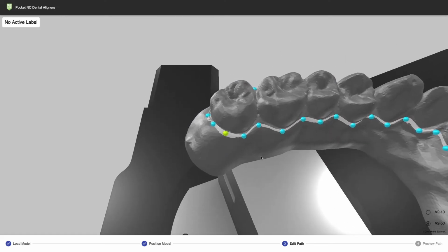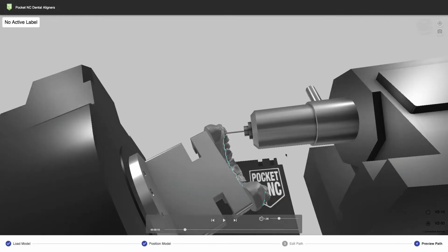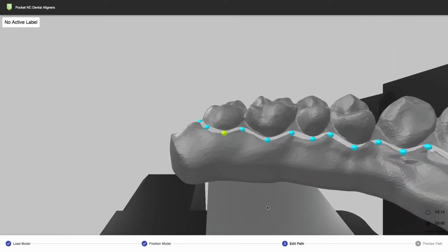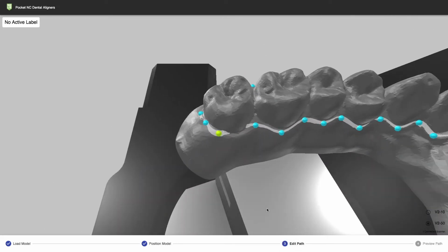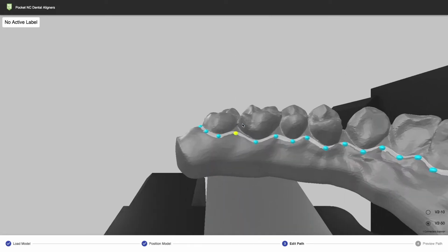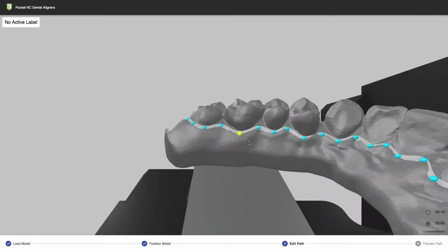When you delete a point, the camera will take the angle of the previous active point, and we know that's good in this instance. So if you go through the process of deleting, it will go to the good camera angle, set the new point, and continue on. So press the point, delete, set the new point.